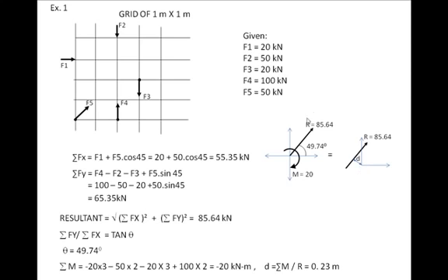In other words, to this body, which is, let's say, 4 by 4, which is subjected to 5 forces, instead of these 5 forces, you can apply simply this force at this location from the origin, and it will do the same job. So that is another way of answering the question, where you have to just work out this d. So this is how you find the resultant of non-concurrent forces.